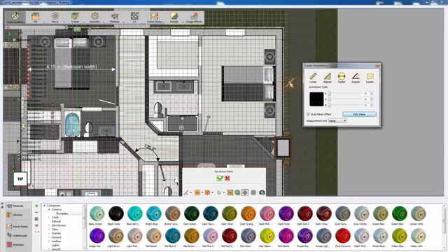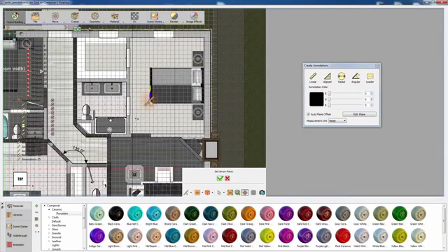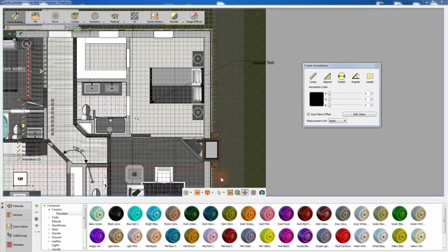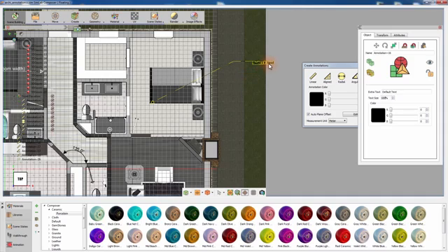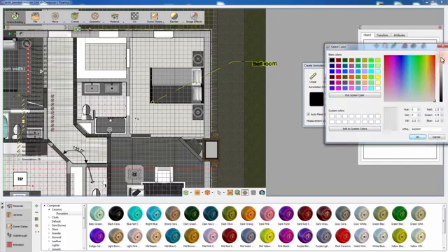Create a leader annotation and click on a surface or an object to create an indicator pointing towards it. You can click several times in the 3D area while moving the cursor to determine the path of the indicator for the leader annotation. Click on the green mark to confirm the creation, then select the created annotation and from the Attributes panel, type in a custom text. Leader annotations are a great tool besides the measurement tool. They allow you to add notes and identities to your design.